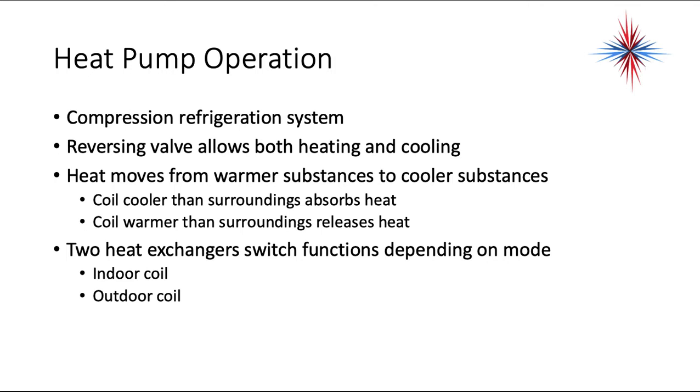Heat pumps use a compression refrigeration system, just like air conditioning does. We add a component called a reversing valve that allows both heating and cooling to occur. Heat always moves from warmer substances to cooler substances. A coil cooler than the surrounding air absorbs heat. A coil warmer than the surrounding air releases heat.